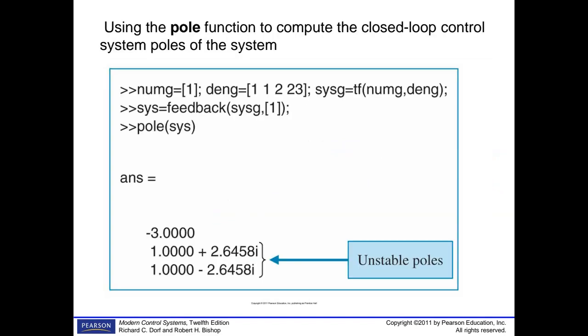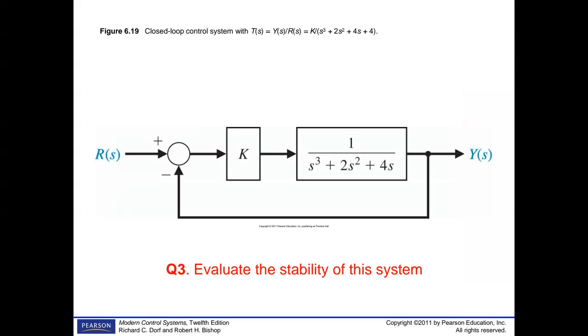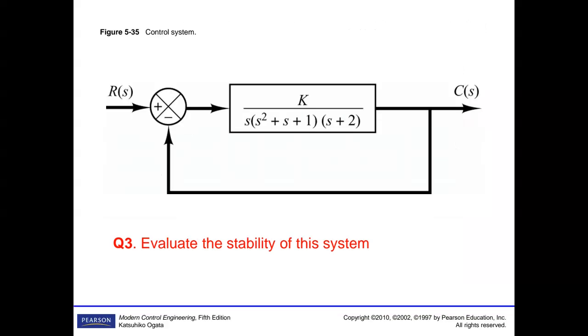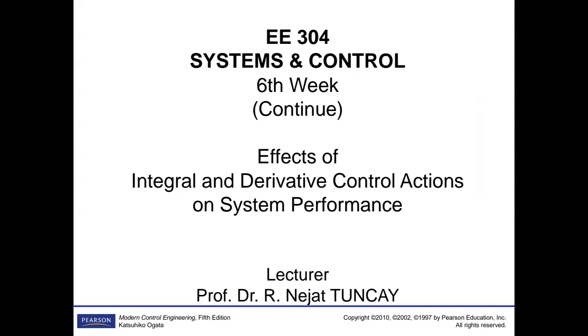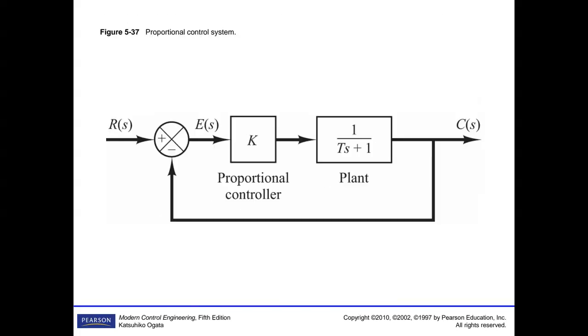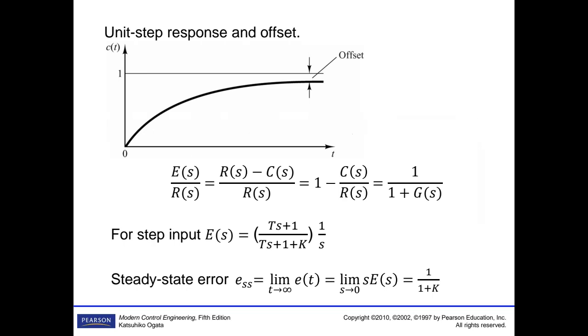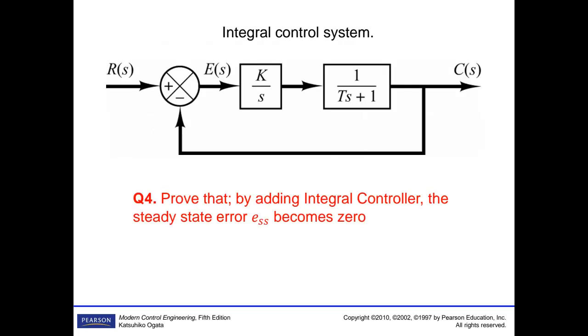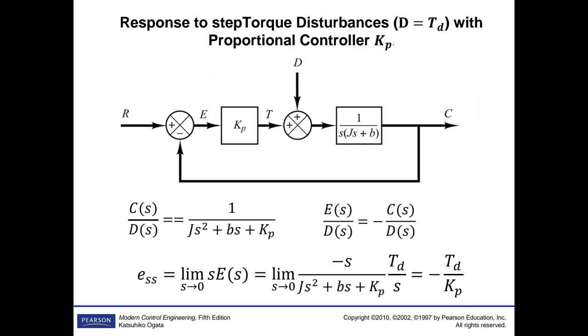PID, proportional controller, error. K over S affects that one, and also KP affects this one, how your disturbance error is affected by KP. KP is actually reducing the disturbance. And also adding an integral makes it 0. So adding an integral is even getting much better.